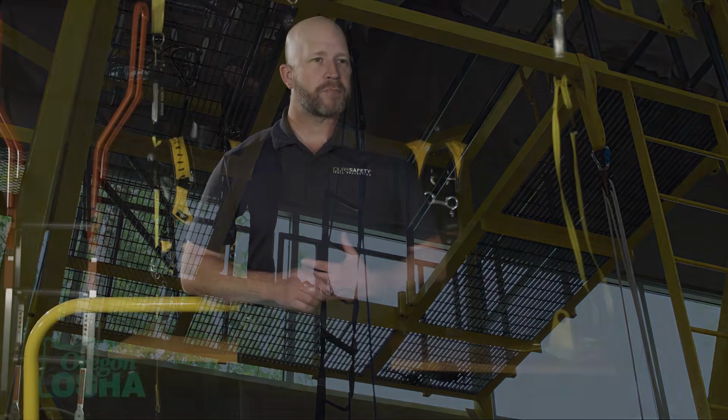With the necessity of inspecting equipment, if a fall occurs, all the equipment, the anchor, the body harness, the connecting device, shall be immediately removed from service. It is highly recommended that if you have a successful fall, you contact the manufacturer of the equipment being used, because many have policies that they will replace fall-used equipment 100% free of charge, only with a little bit of paperwork and understanding of how it was used.